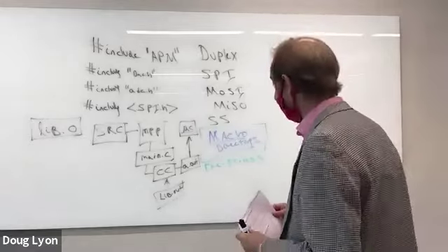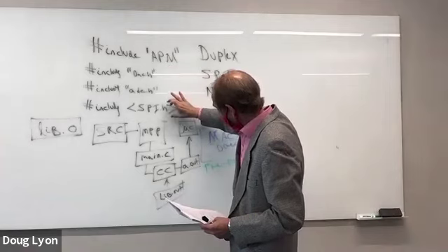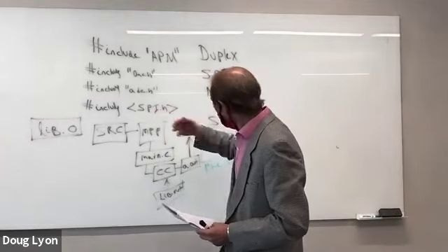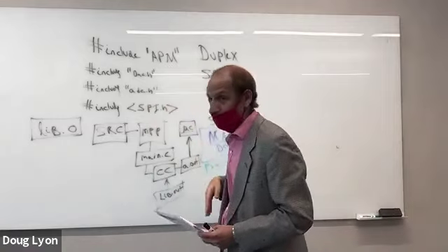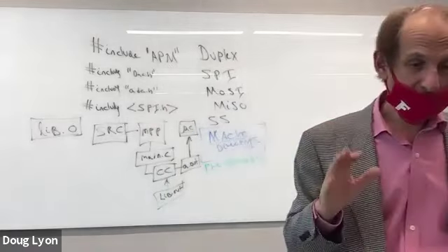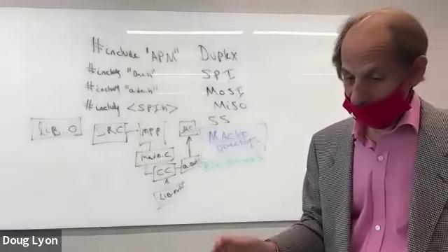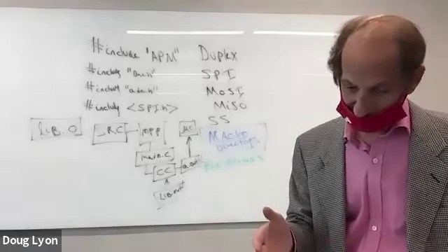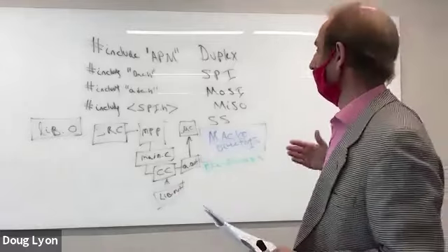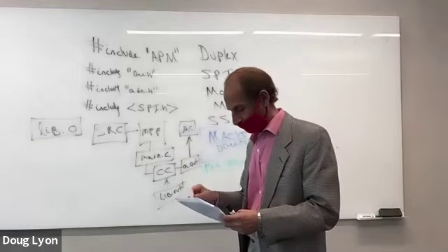So those are the macro directives that we've seen so far. This is what we've seen in the lab. We actually used, I think, something that looked like this, only it was for servo.h. So what's in the servo.h file? Well, the answer is it's a declaration of all of the subroutines and what they take. So what they return, functions that return values of different type, and also the arguments, the parameter list that the subroutines take.